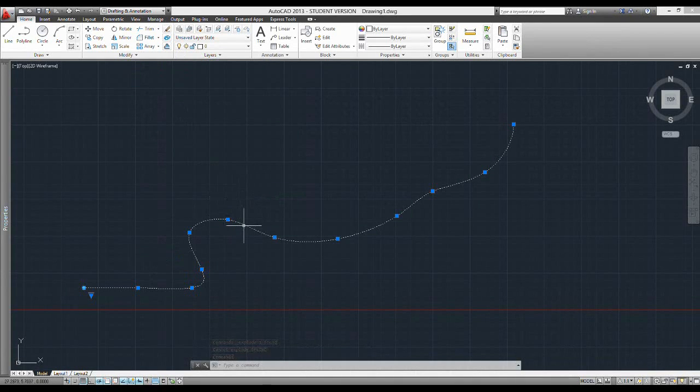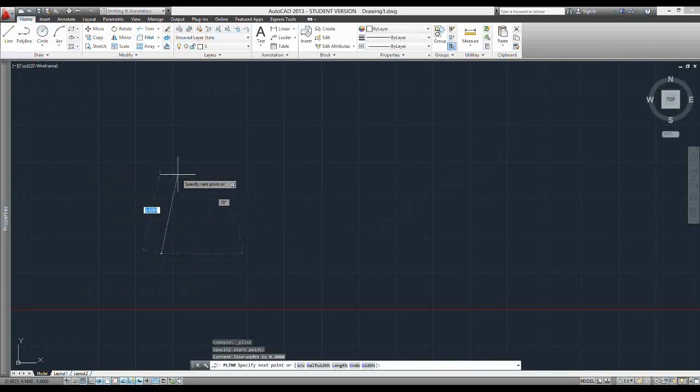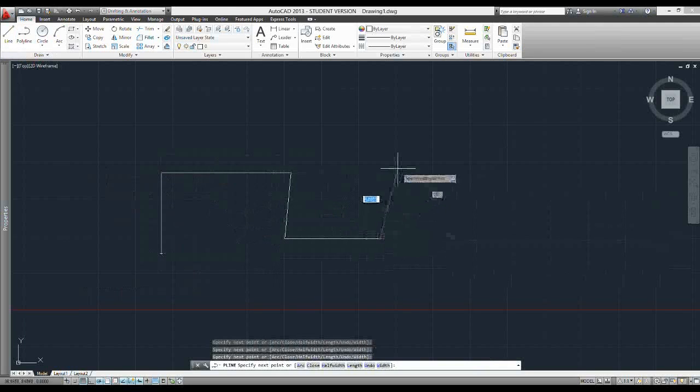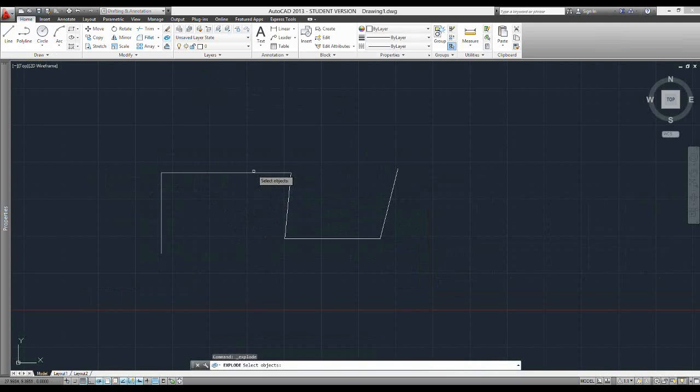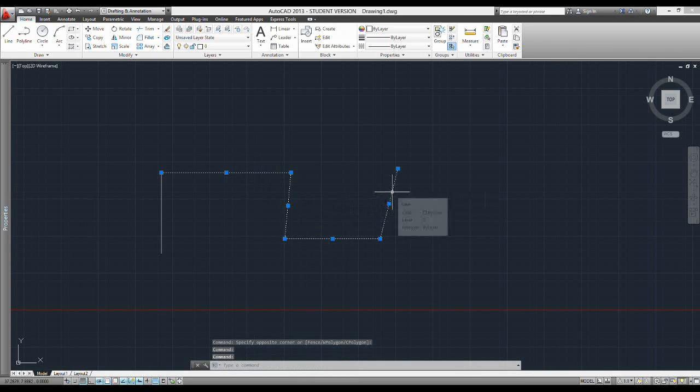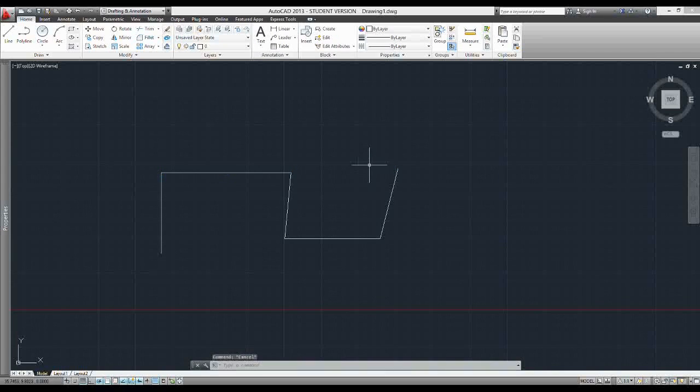What if, though, I had a polyline of similar make and exploded that? Okay. That will break up the polyline into its individual lines, arcs, or etc. Okay. Which will actually be lines rather than little polylines, like with the spline where it would break up into smaller splines.